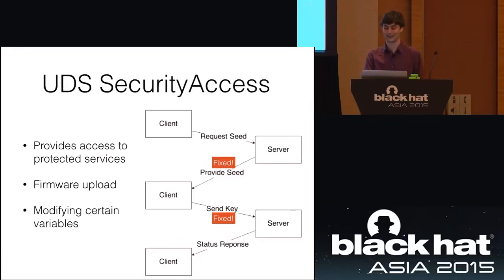But the thing that's really great about it is that both the seed and the key are 16 bits long, which means you can brute force the key space pretty quickly. They've sort of tried to stop you from doing this by putting in a delay, so you can't just send all the requests all at once. But it's not that long, really. It's not something you can just jump in a car, plug in, and crack it. But if you have access to the car, or if you've taken over a controller in a car, it's pretty much maybe a couple days worst case to get access to that.